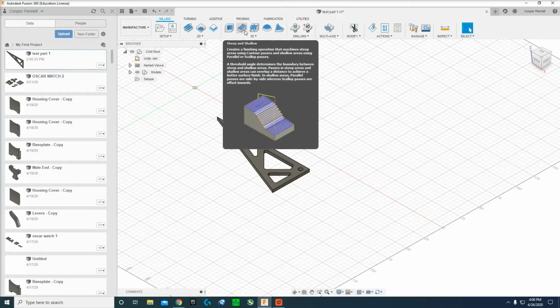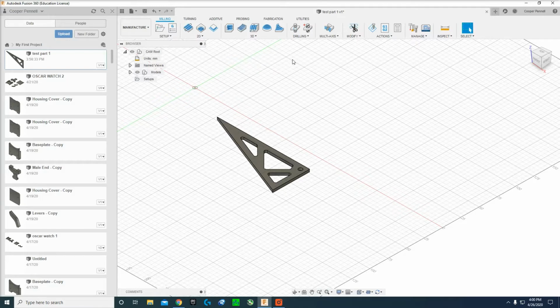These are the types of toolpath that you're going to be machining this part with, right? There are all sorts of ways you can cut it apart with a CNC router. You can drill something, you can cut it on a bandsaw, you can mill it, all that kind of thing. And a CNC router can do a lot of those things just by itself, and that's why it has all these different options. So you can see there's drilling options.